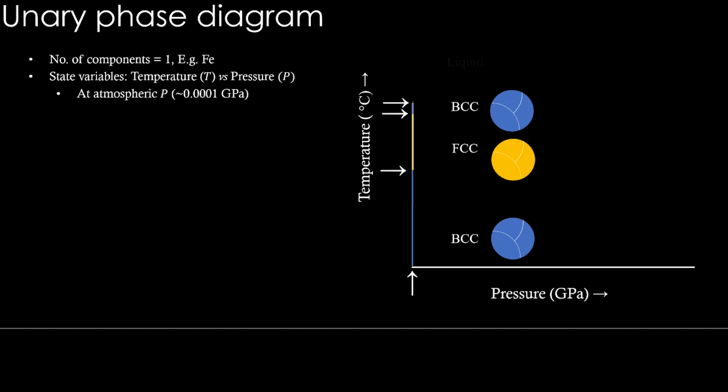And beyond a temperature, BCC finally becomes liquid. So in solid state itself, there are changes in pure iron. So once it becomes liquid, so this is the liquid structure, there are no grains. So there are 4 different phases at different temperature ranges.